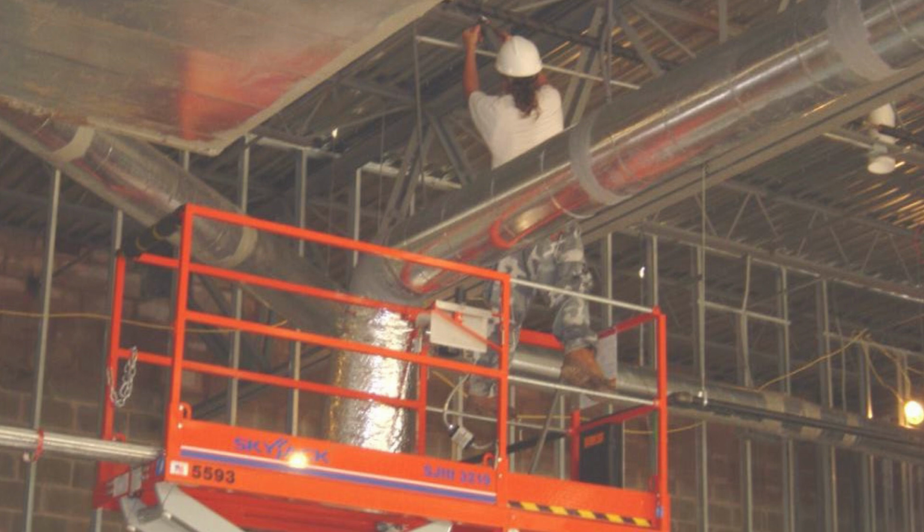These scissor lifts have their fall prevention built in. That's your handrails. All right. In the manuals I've read, and I recommend you read your manual because your manual may read different from the ones I've read, as long as you maintain inside that handrail, you're not required to wear a fall arrest system or fall prevention system because you've got a top rail and a mid rail.